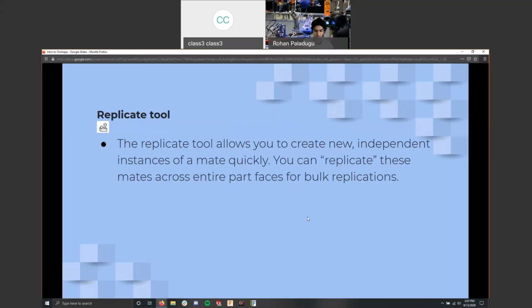So let's say we have a drive rail extrusion, and on the top there are all these holes for rivets. I want to put a belly pan on, and I want to use each one of those rivet holes to connect our rivet from the belly pan to the drive rail. Well, it's going to take a lot of time to get all of those rivets individually placed, right? I have to mate this rivet, import another rivet, mate this rivet, and do that again and again. It just takes a lot of time.